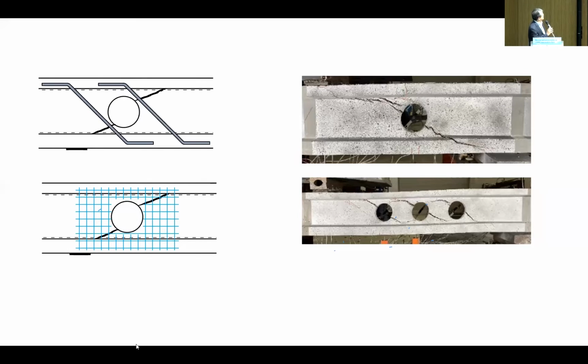Thank you. Okay, now we have a question in the chatting box. What percentage content of recycled aggregate and waste glass aggregate do you recommend using in UHPC? From our research, around a 10% replacement ratio gives us acceptable mechanical property and durability, for example, alkali reaction and also some freeze resistance tests. More than that percentage gives us some adverse effect. That means a disadvantage is shown.